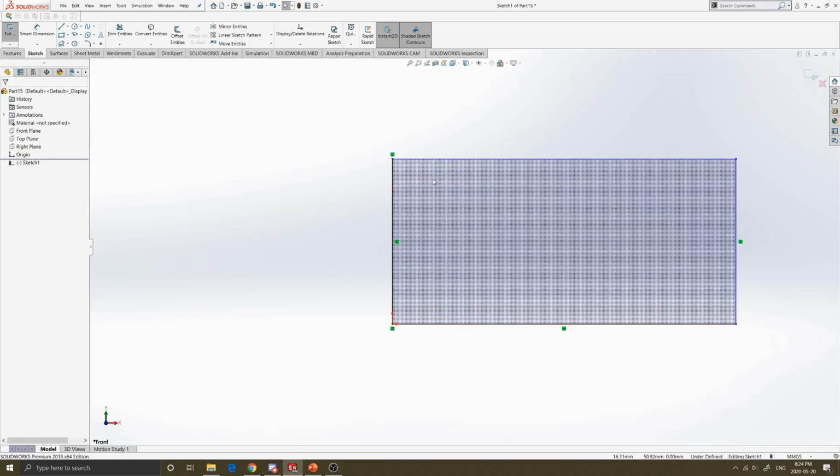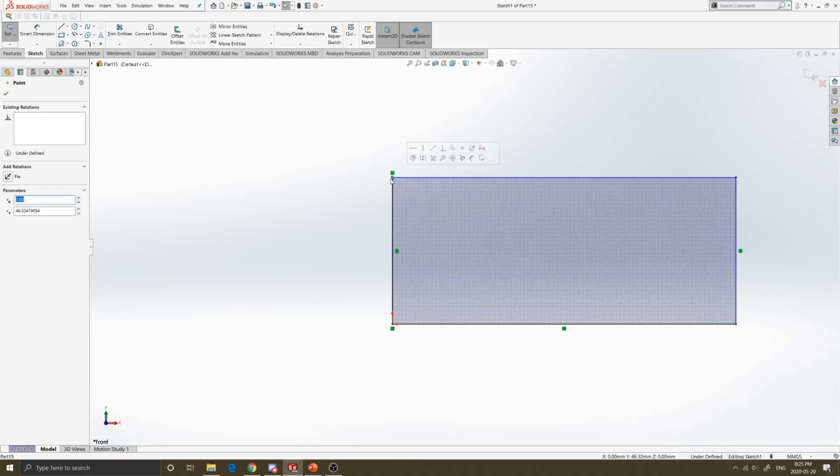Having fully defined sketches really helps rendering bigger parts. As you make more parts and put them into larger and larger assemblies, it gets harder on your computer. Let's say the computer knows that your line is vertical and that it's here, but it doesn't have a defined space in memory saying the line has to stop at, let's say, 50 millimeters from here.